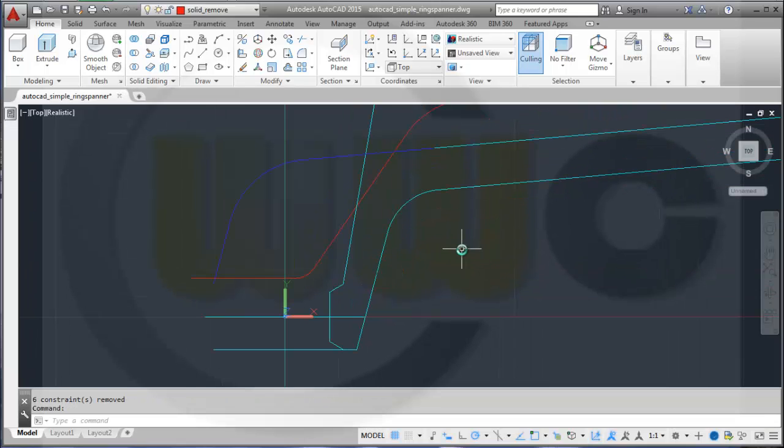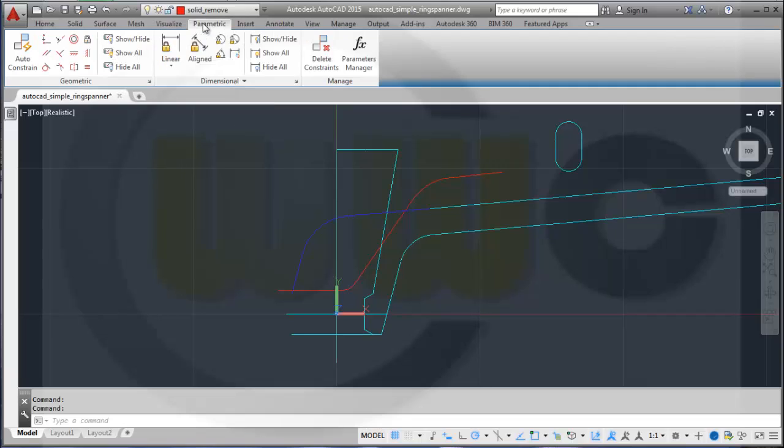Yeah. I need some dimensions. There should be an angle by 70 degrees. Oh, that's nice. I thought there should be auto constraint tangency. Yeah, I better change it to a polyline, so I lost these, so maybe I auto constrain it again. Yeah. Hide them, and now I can do my dimensions.